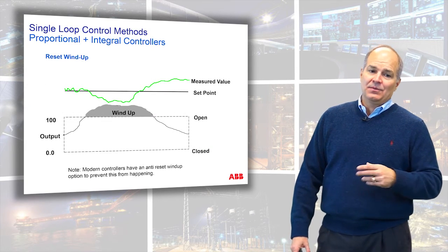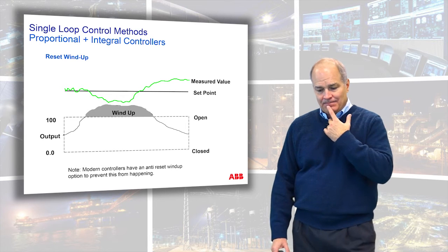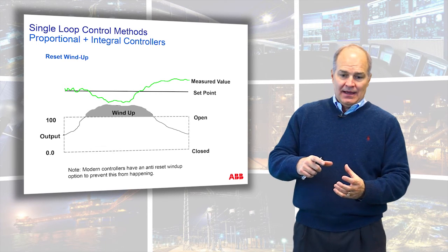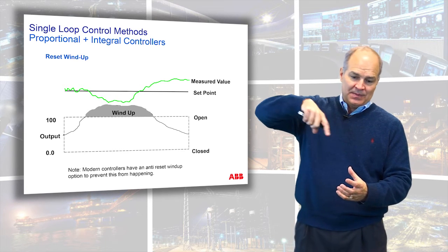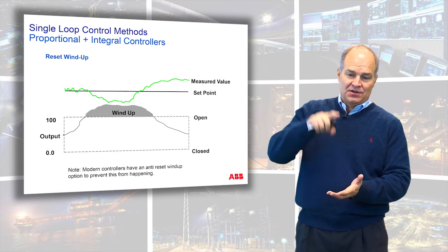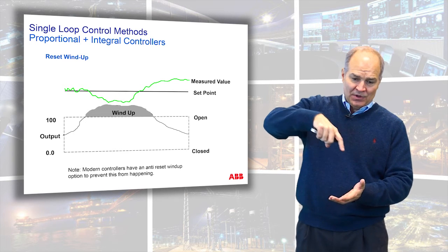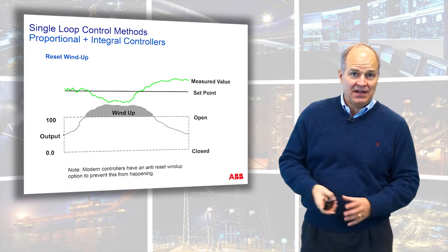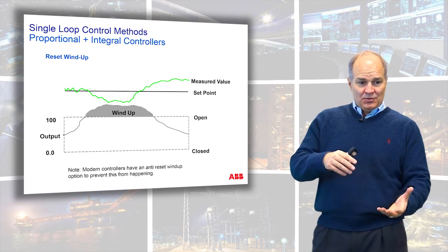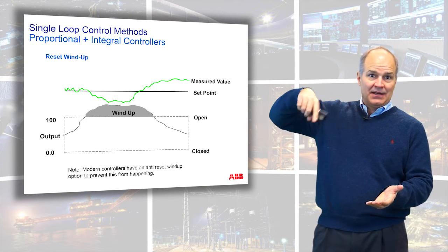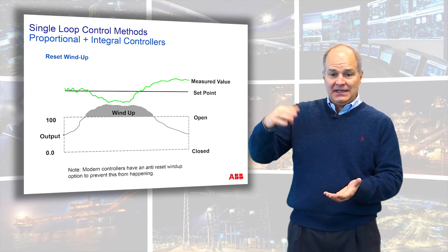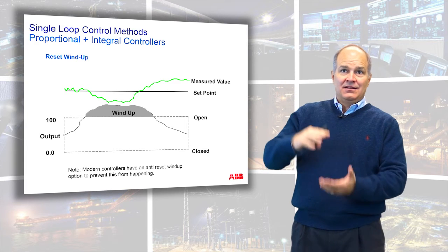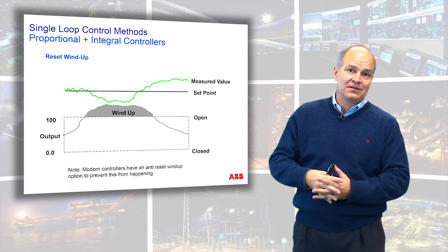One of them, when we first started, was called windup. Imagine you had a spigot and you were trying to open it, but let's say the spigot had 10 turns from stop to stop. But once you got past the second turn, the velocity of water coming out of it didn't change. But because you wanted the bucket to fill up faster, you kept spinning. So from turn 3 to turn 10, nothing happened, okay? So you're now outside the control range of that particular device.